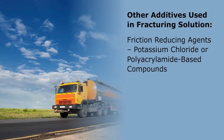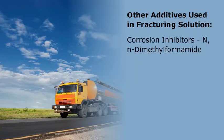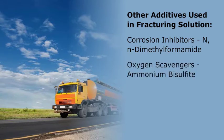Friction-reducing agents, also described previously, such as potassium chloride or polyacrylamide-based compounds, are used to reduce tubular friction and subsequently reduce the pressure needed to pump fluid into the wellbore. The additives may reduce tubular friction by 50% to 60%. These friction-reducing compounds represent the slickwater component of the fracking solution. Corrosion inhibitors, such as N-dimethylformamide, and oxygen scavengers, such as ammonium bisulfate, are used to prevent degradation of the steel well casing.